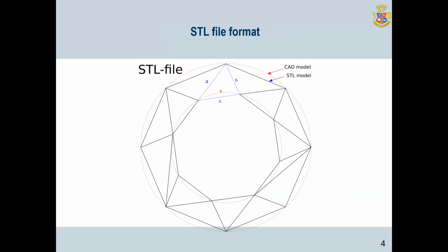Slicing software works with different file formats, but the stereolithography file format is one of the most popular. It is supported by most computer-aided design packages, and it is widely used in most rapid prototyping additive manufacturing technologies. STL files only describe the surface geometry of a 3D object without any representation of color, texture, or other common 3D model attributes. Information about an object is stored as a list of triangular faces that describe its surface and their normals. An STL file can be text or binary.